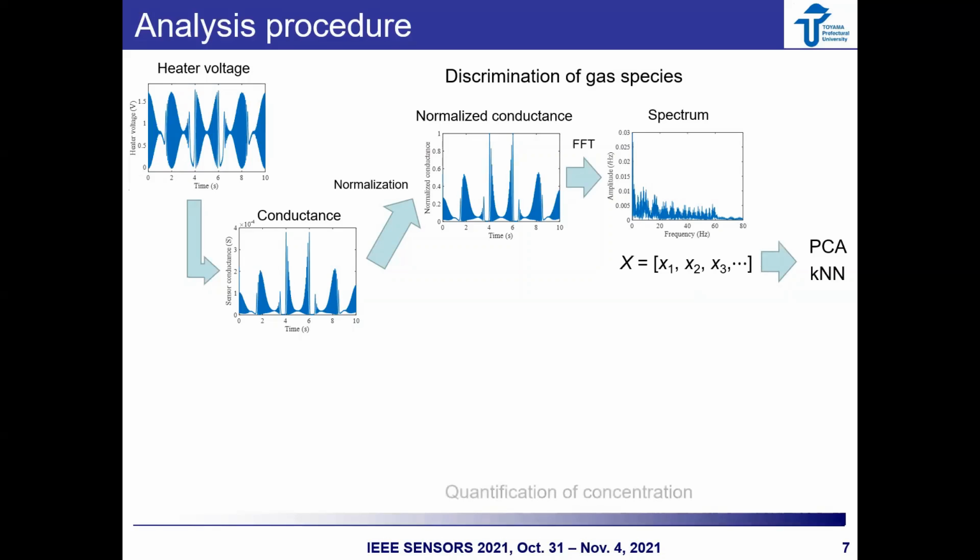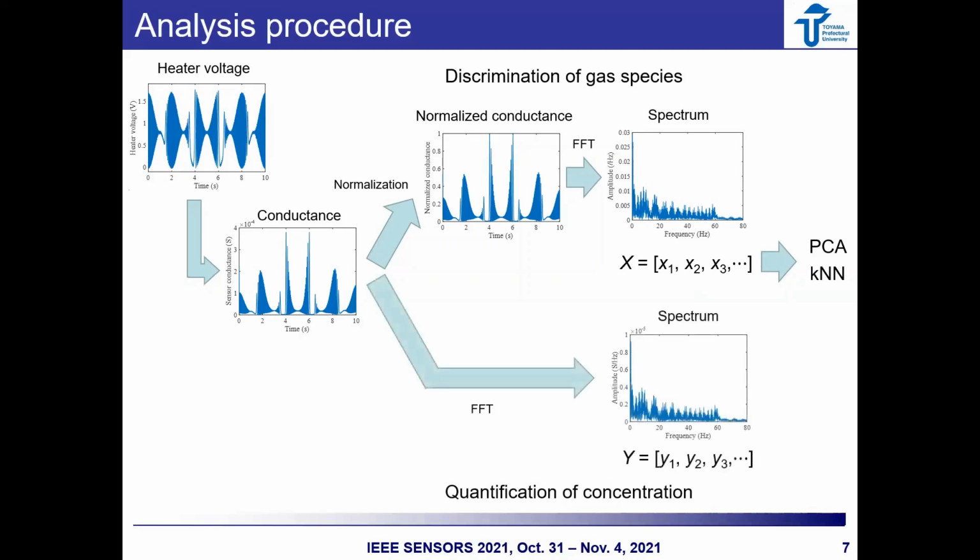On the other hand, in quantification, FFT was conducted on the sensor conductance without normalization to obtain the spectra. After carrying out PCA on the data vectors, we examined the relationship between the PCA score and the gas concentration.